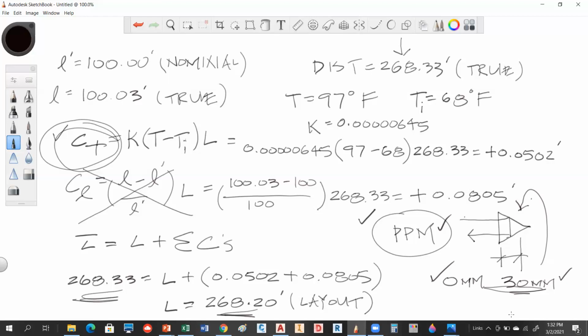It's possible, sure. That's why it's really dangerous when you get equipment from different manufacturers. People buy all these prisms all the time and they just assume that their total stations are set to 30 millimeters. That's what a lot of people use, but that's not necessarily true if your prism's set wrong. So you gotta watch that. When we get to lab on Thursday, if you remind me, I'll show you. Usually on your prism, it'll tell you what the millimeter stamp is, and we'll look at the parts per million correction and the reflector constant for you, just so we can take a look at that.